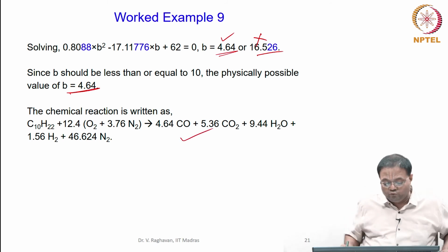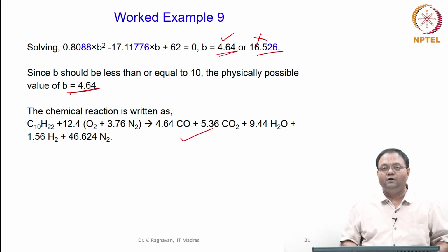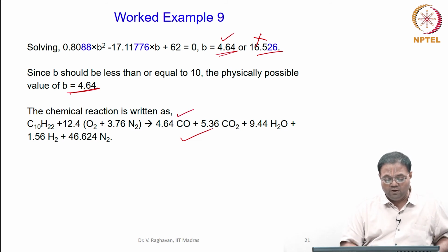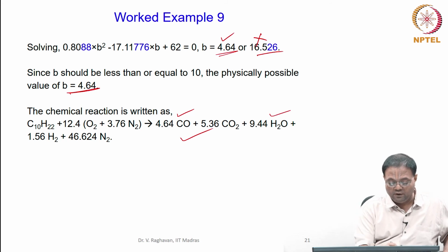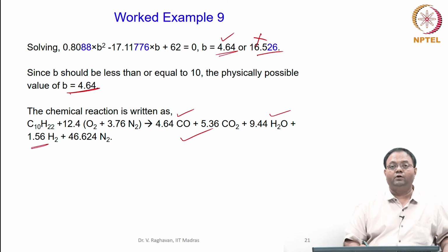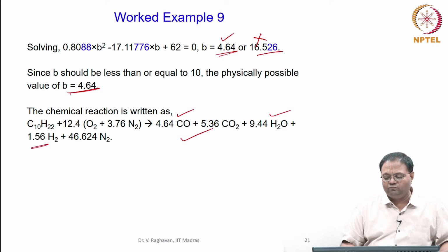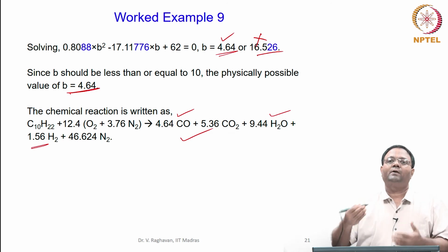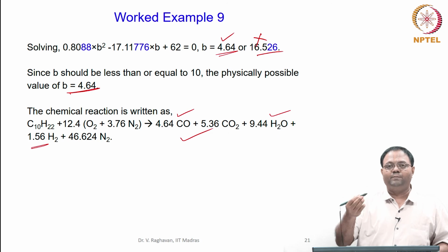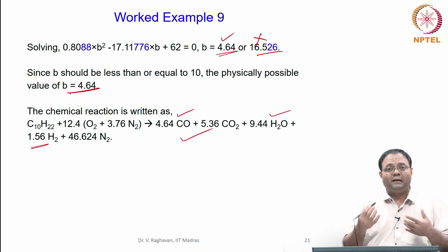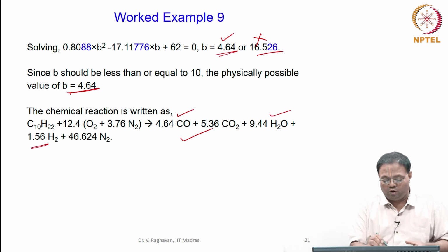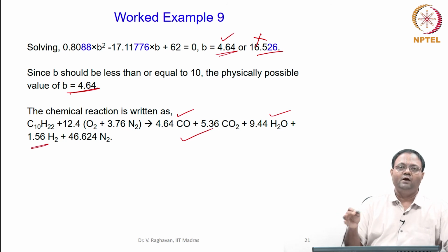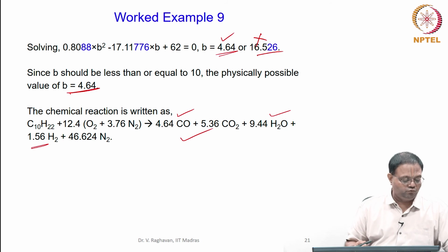So in this we have used equilibrium to find the proper products at a given temperature. When temperature changes, these values will change. You can see that more dissociation has taken place for CO2, and also a significant amount of hydrogen is present. So you can also use additional equations. If you want to basically have say OH or H or O, you can add them and you have to use an appropriate number of equilibrium equations, and say Kp1, Kp2, Kp3 etc. can be used to solve that. So multiple equations also can be used to solve for a particular composition. So you can use n number of product species and n number of equilibrium equations to solve them.